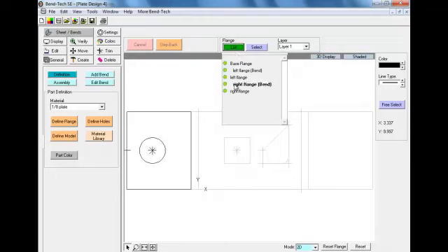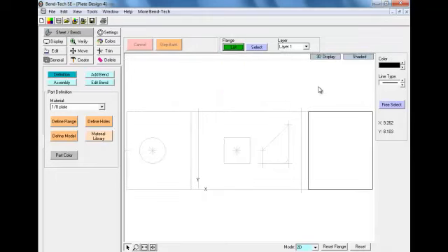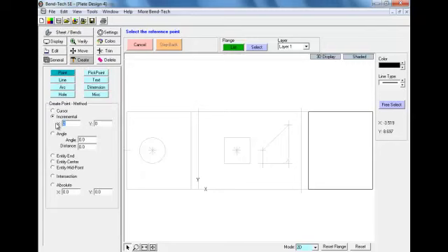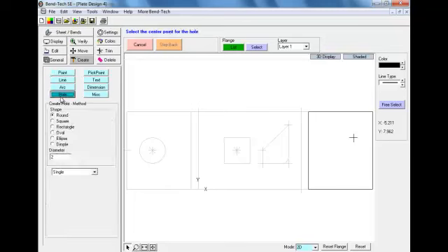We're now going to move over to our right flange, and we're going to select a rectangular hole in that flange. So we need to start out by creating a point. We're going to select the far right corner and drop on our new point. We can then create a hole.